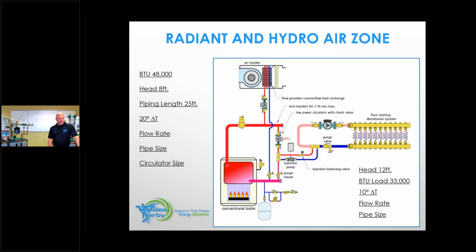So based on 9.5 and 4.8, what circulator did we come up with? Well, Jen said a 007 as the minimum. 007. I'll take a 007E. I'll take a 0010. I like the 0010 better than the standard 007 in that application. And I like a 0015 E3 on high. The 0015 E3 is a pretty universal circulator.